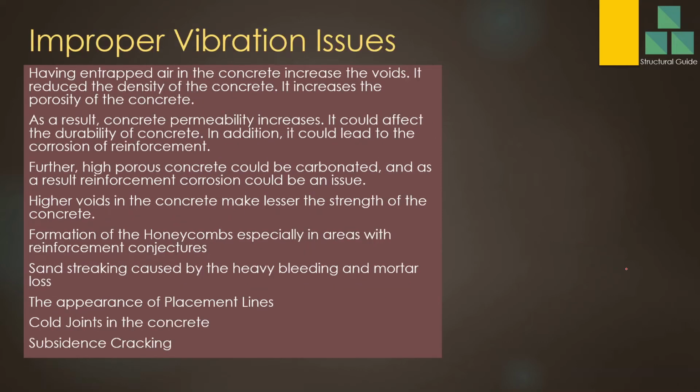Improper vibration issues are very important to us. If you do the concrete vibration improperly, there will be issues. Definitely there will be issues related to strength, and there are many more. Having entrapped air in the concrete increases the voids. It reduces the density of the concrete and increases its porosity. The increase in porosity will be an issue for us.